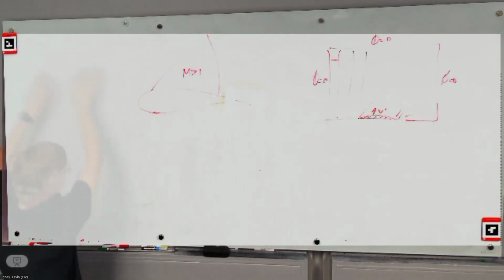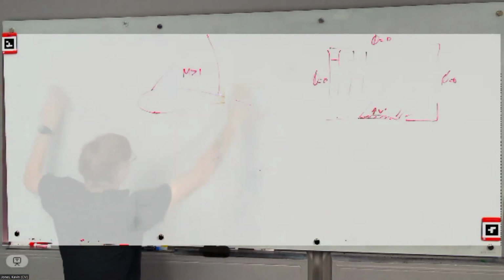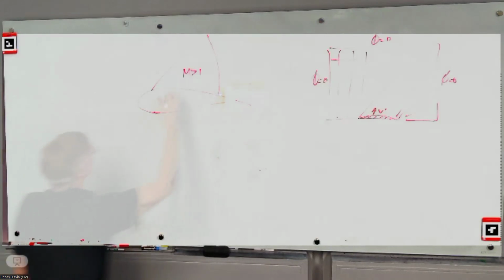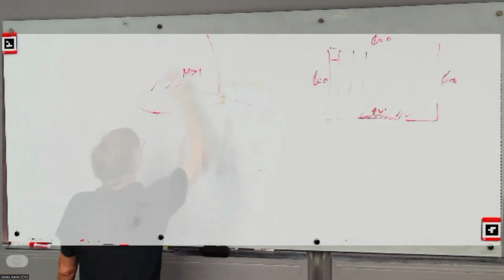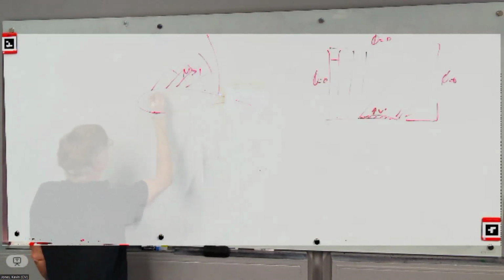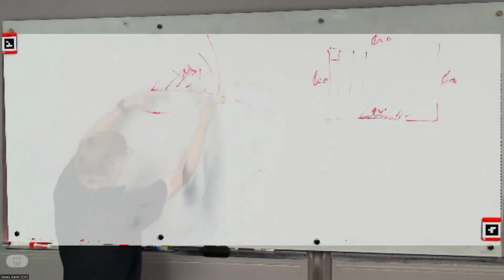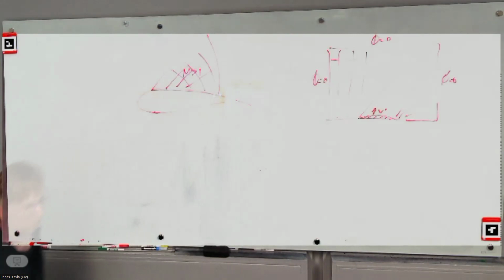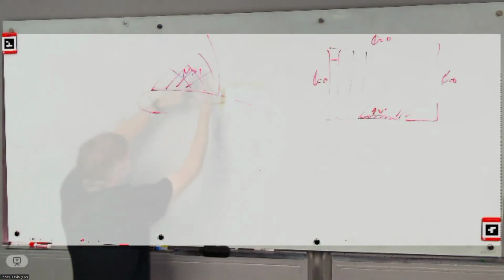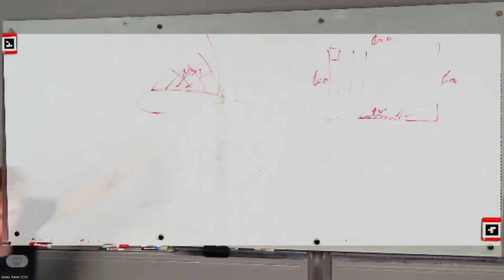And so they were running potential flow out here in this whole region, and then inside of here they would do this method of characteristics, and they would slowly, essentially, tweak the shape of the surface. Usually it got flatter to try to shrink that supersonic region and make the shock weaker. But again, I think with Navier-Stokes now, that's not super common.